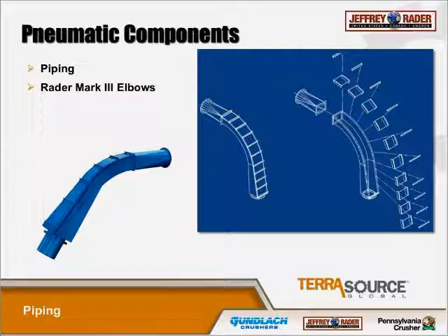As you can see in this image, the high impact areas are easily removable and replaced. We also offer proprietary blends called R35 cast segments, which are extremely wear resistant. It's not an exact thing, but it will typically see 6 to 8 times the wear life of AR200. That gives you a frame of reference. You don't want to be changing these things out very often. It's just more downtime, and loses more money.